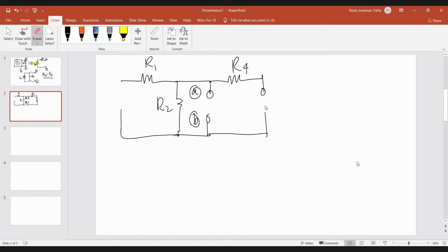So how about your IN, or the short circuit current? We connect the voltage sources here. This is V1 and this is V2. And when we say IN, or short circuit current, we simply connect these two terminals here. We short this out, okay? And then you solve for the current IN going above.